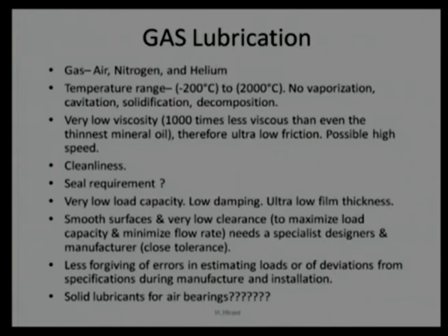So, gas lubrication requires extreme optimization with all calculation of unevenness, or we say that in all situations it should be working, otherwise it will turn out to be an unstable situation. A slight change in the load, and surfaces may collide against each other, and there will be high adhesion between surfaces. That will be problematic. That is why I say that it is less forgiving of errors in estimating the loads. If the load estimation is not proper, then there will be a problem.